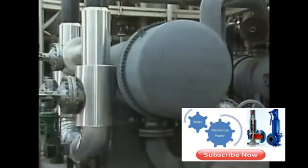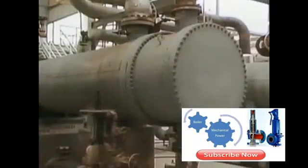A compressor system often has a cooler that is located in the discharge of the compressor and is referred to as an aftercooler. The aftercooler shown here is a shell and tube heat exchanger. In this case, the compressed gas flows through the tubes in the aftercooler, and it is cooled by cooling water that flows around the tube.